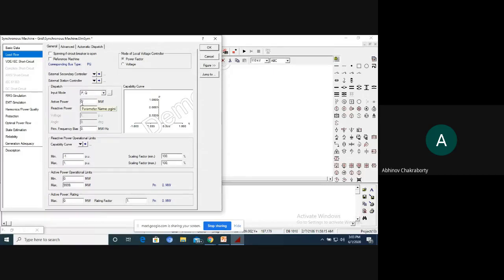Over here, now I'm making a probabilistic reverse engineering. 3 megawatt assigned to one load, 4 megawatt assigned to other load. I might have some expansion in future also. Keeping that in mind, I'll be trying to have an 8 megawatt generator. And MVAR, already it's 1 plus 1, 2. So I'm taking it to 2 MVAR for the system.